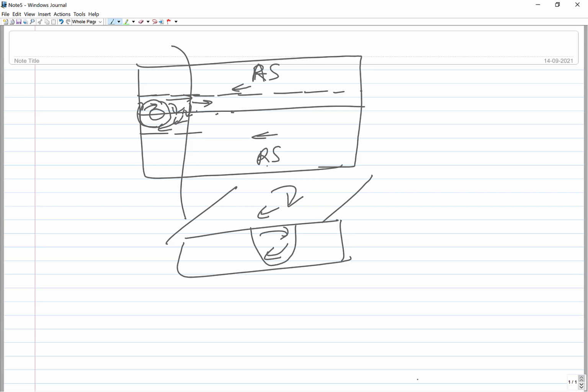So in order to develop the metallic continuity all along the weld line, you have to move the workpiece through the tool at a particular speed, so that the entire joint length is covered, and the joint is made all along the weld line which is to be joined.